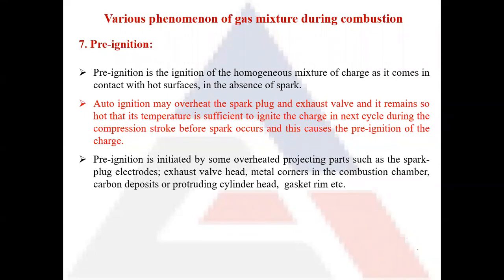So the homogeneous mixture, when it comes in contact with these glowing or hot surfaces, in the absence of the spark, ignites the fuel, and a flame front starts to form. Now this flame front, caused by these glowing surfaces or hot surfaces, is known as pre-ignition.